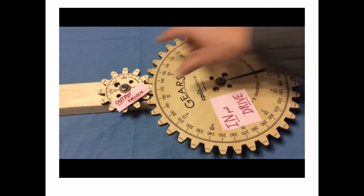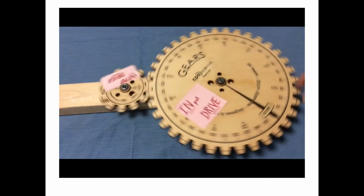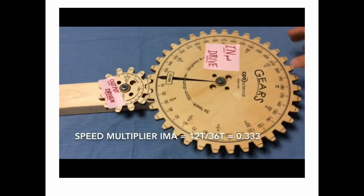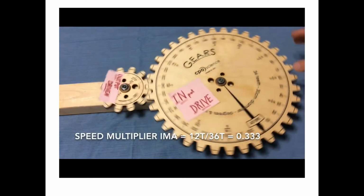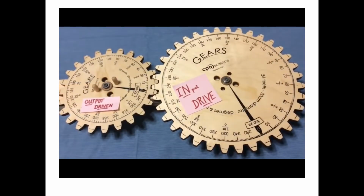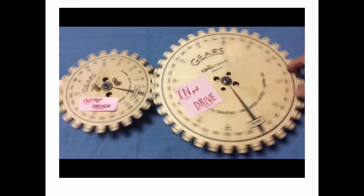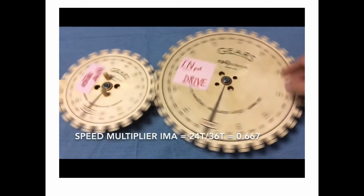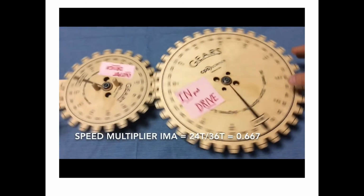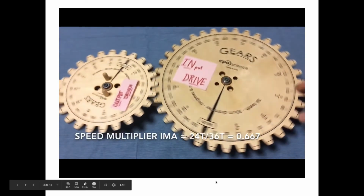So 36 teeth to 12 teeth, that little one is spinning 3 times as fast, 36 over 12. That's a mechanical advantage of 1/3. Here's a 36-tooth, 24-tooth combination, which means that the little one is spinning 1.5 times as fast, and the mechanical advantage is 2/3. Remember that any mechanical advantage less than 1 is a speed multiplier, and a mechanical advantage greater than 1 in these cases is a torque multiplier.